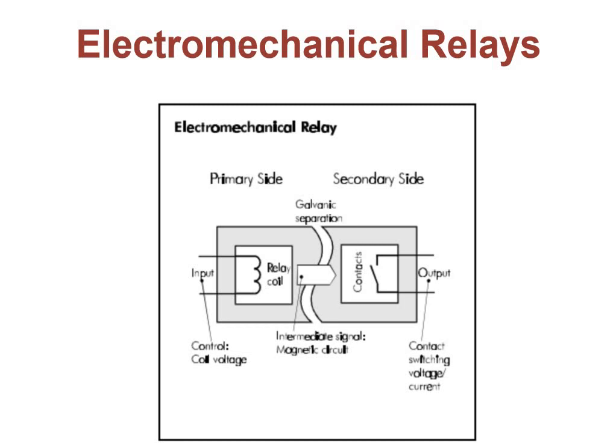Then thermoelectric relays are also there. In these relays, the input energy on the primary side hits a bimetallic part which actuates the contacts mechanically. Piezo relays are also there. In these relays, the contacts are operated mechanically by the piezoelectric effect. Signal relays are also there, power relays are also there, contactors are also there.